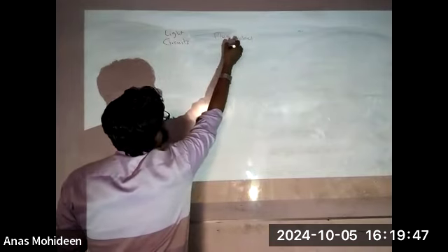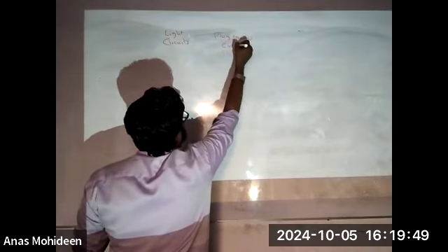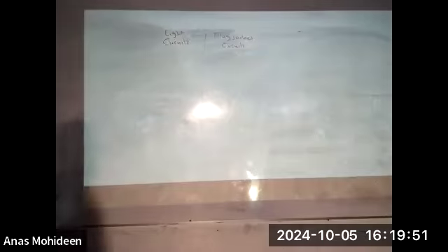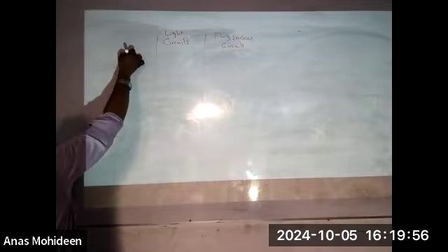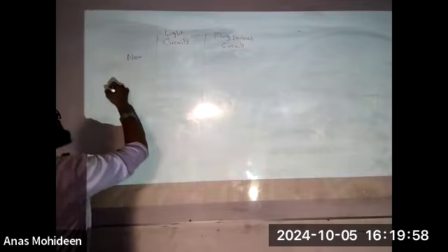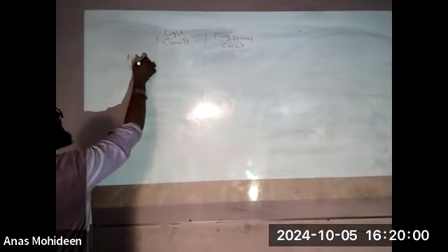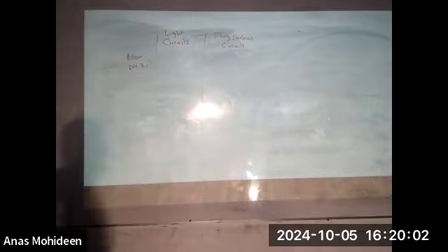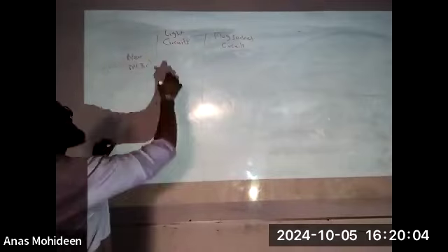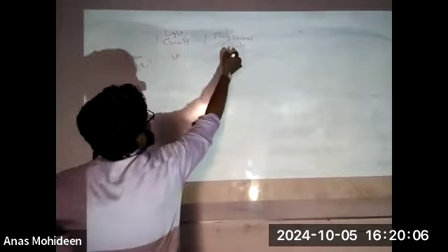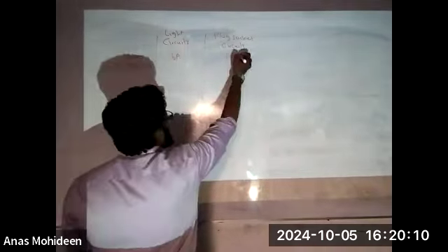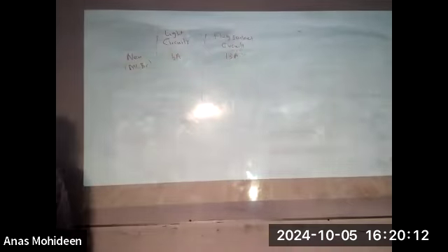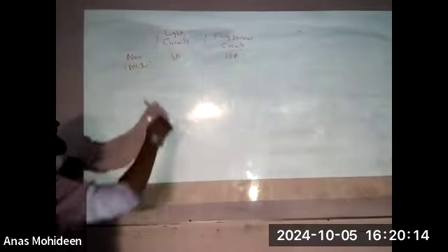And then the plug socket circuits. We write it down on a writing book. Light circuits, in the new house that I am speaking about, the modern ones, we have MCBs. So 6 amp current is provided for lights, and here 13 amp current. 13 amp current.